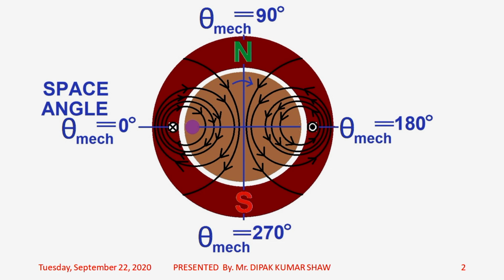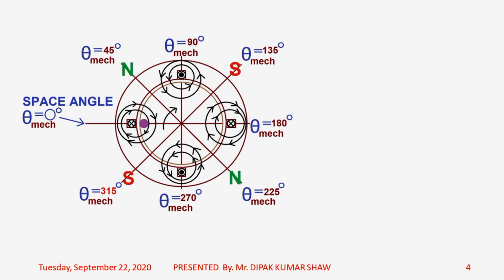Let us now think of this particular case. You can view on the screen that 4 poles are developed on the stator core right now. So what has been done? We are using 2 coils. Earlier there was only 1 coil, so there were 2 coil sides. Now you can see there are 4 slots created on the stator core. These 4 slots are accommodating the coil sides of 2 separate coils. A coil has got 2 sides, so if the number of coil sides is 4, then the number of coils will be 2.